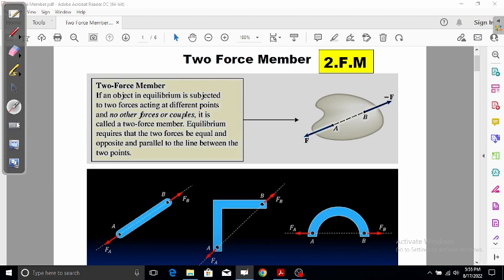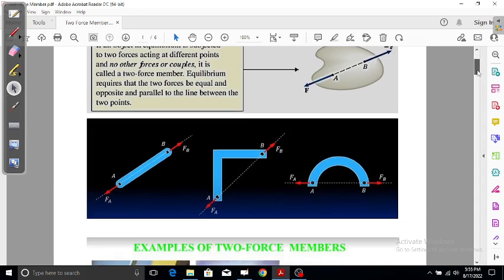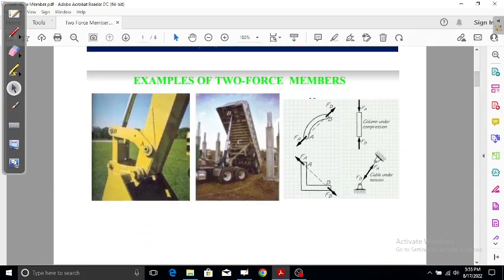So these are some examples of two force members, and if you want we can get more examples out of it. Again, these two force members are very widely used in, as I told you, a lot of different industries. They are used especially in dumpsters in everyday construction industries, in mineral extraction where you will see dumpers, and in excavators, mobile cranes, bulldozers, dumping trucks, and front end loaders, which are all constructed by combinations of these two force members and three force members.